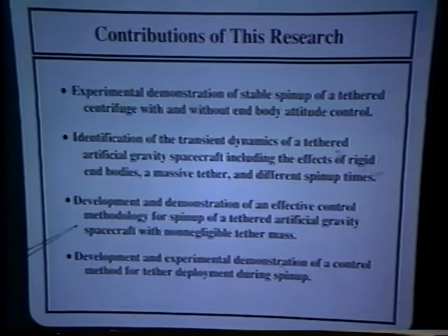Thirdly, the development and demonstration of an effective control methodology for spin-up of such a spacecraft with non-negligible tether mass. And lastly, the development and experimental demonstration of a control method for deploying the tether during the spin-up maneuver.